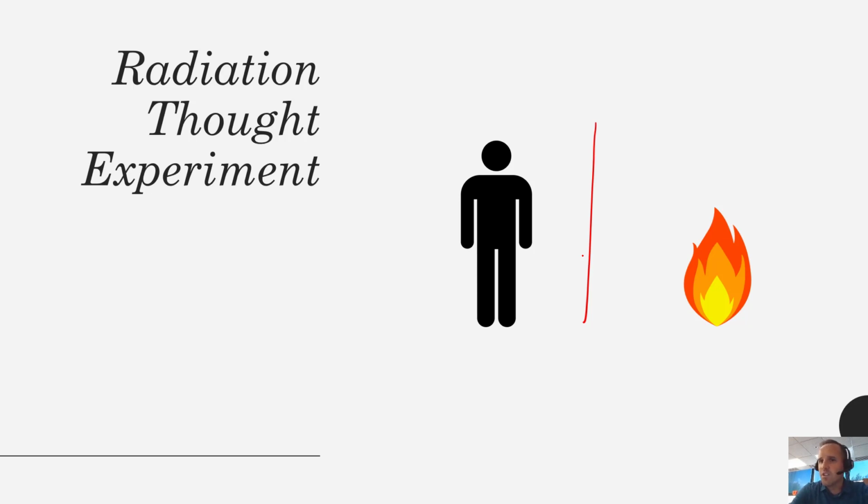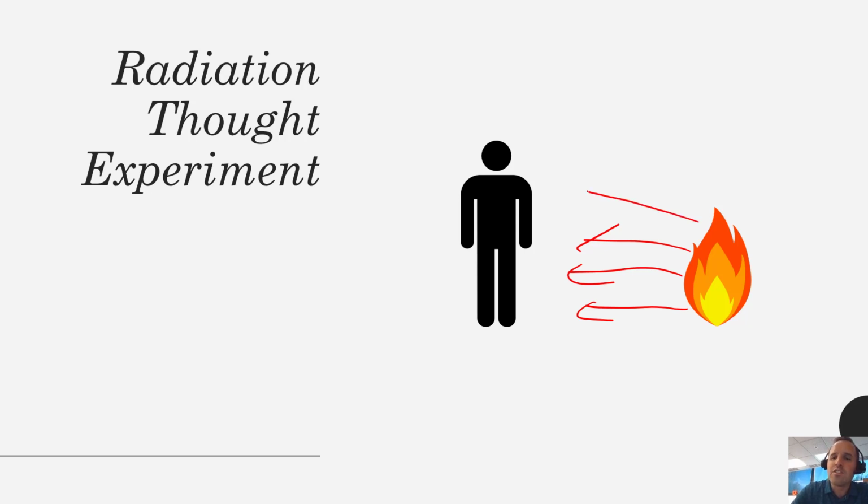So this is a surface-to-surface phenomenon. If we thought of this fire as a surface and you as a surface, some of the photons and electromagnetic energy is going to be emitted from that fire, and you are going to intercept some of it, which would cause your body to absorb some of that heat to the point that you could physically feel it. And even though there would have to be air for the fire to be burning, the heat transfer doesn't require that air in between.